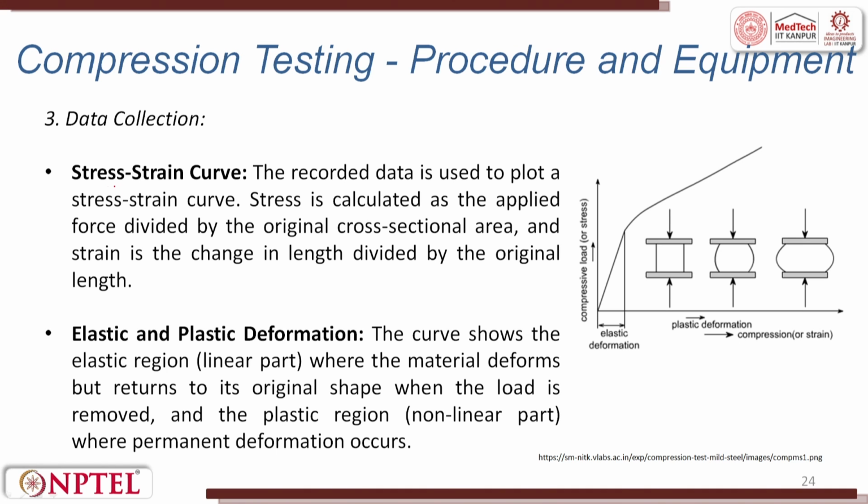Data collection, stress strain curve, just like we have discussed in the tensile test. This recorded data is used to plot a stress strain curve. Stress is again the applied load divided by the cross sectional area, and strain is the change in length divided by its original length. Elastic and plastic deformation here.